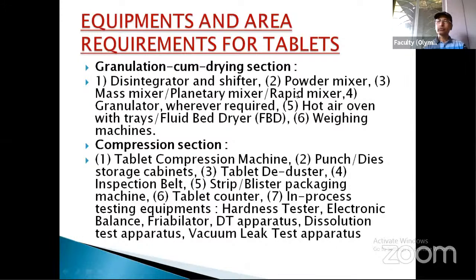And accordingly, you have to adjust your hopper from where the powders or granules are coming to the dies for punching and making the tablets. Then you have to adjust it such that the proper amount of powder is coming to give the required weight of the tablet. So this is also a very important test. For this purpose you need the electronic balance to see the weight and weight variation.